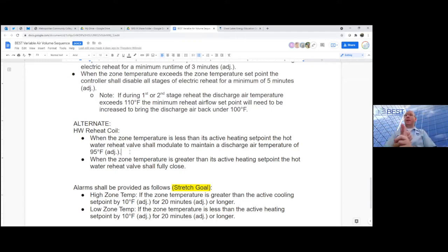One, it becomes very ineffective for heating your space, except right up at the ceiling level, which we very rarely care about. And it also means that we are dumping a lot of energy to heat that air and immediately returning it back to our air handler, which is going to spend energy to remove that heat from the air. So we are really defeating ourselves both from a comfort standpoint and an energy usage standpoint.